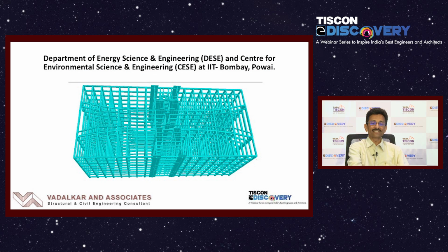Now I will show you some pictures of the structures which we have designed. This is the framing plan of the building. You can notice the lift cores and the other central cores, which give the lateral resistance to the building, at the central portion of the structure, and there are wings. Initially the building was designed as a butterfly shaped building. You can see these wings with the normal column frames on either side of the building. But slowly, because of the requirement of more area, it has been closed and now it has become a box-like structure again.